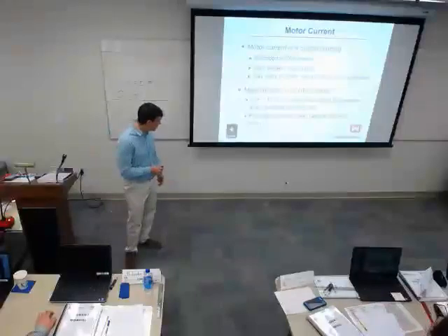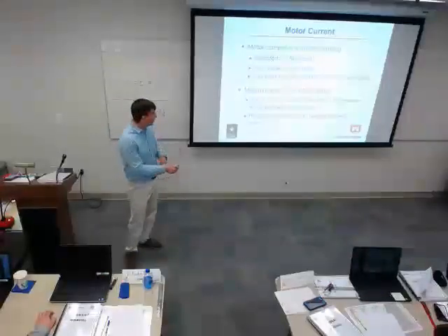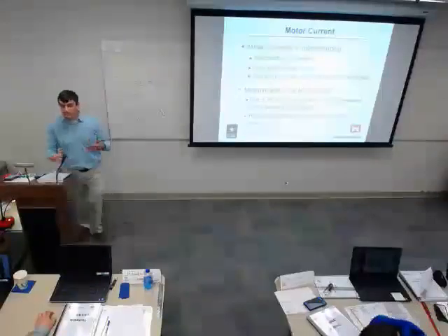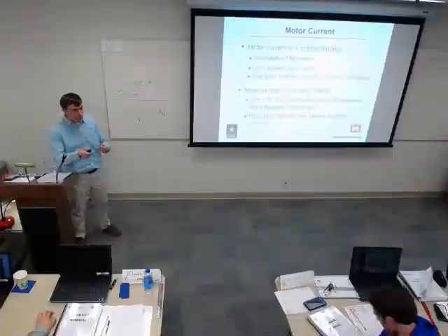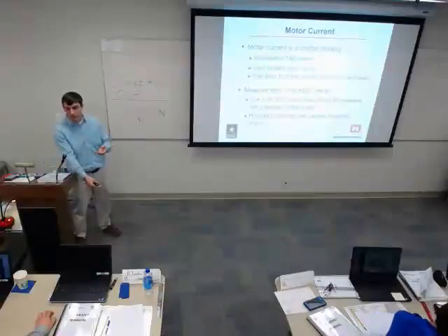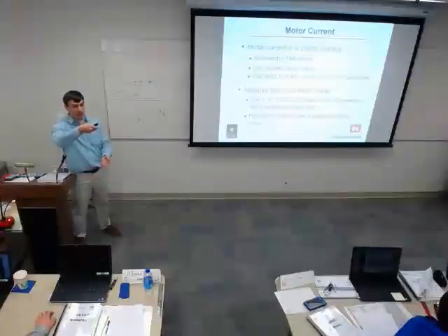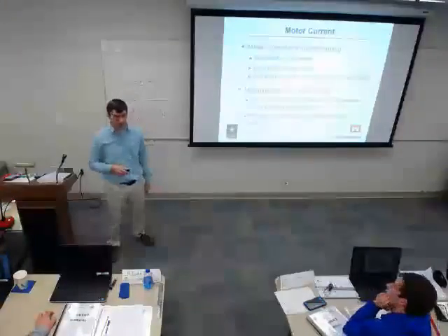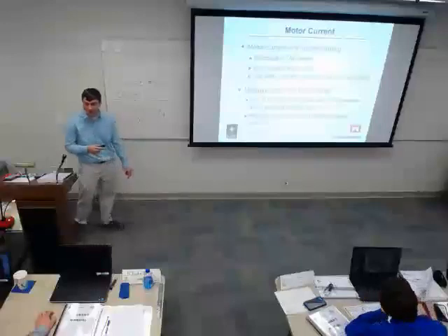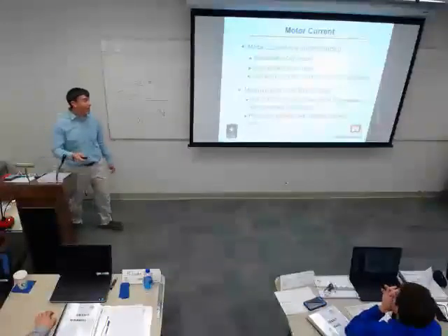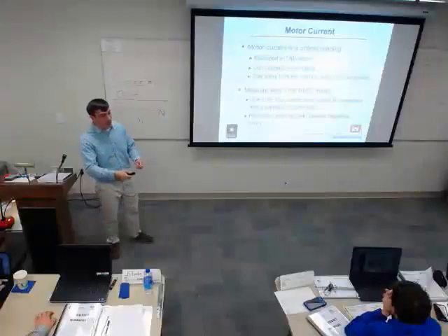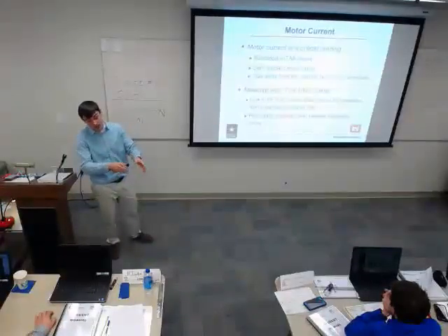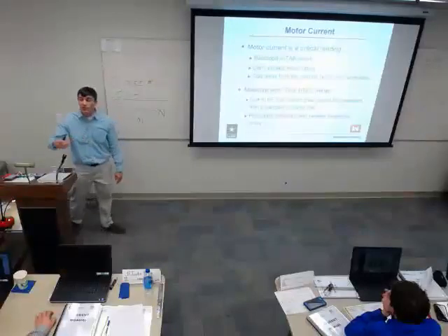Talked about power factor. And like he said, when you go through a VFD, some funny things happen electrically. I can't explain it to you, but you're not going to get good readings if you're trying to read the power on the other side of the VFD. You have to be reading it on the top side of it, because whatever it's doing to create a different frequency is outside of my electrical knowledge. If anybody else has good knowledge on why that might happen, feel free to help us. But I just know that if you read the voltage on the other side of a VFD, it's not going to be correct. It's correct for that motor, but the VFD is changing the frequency.